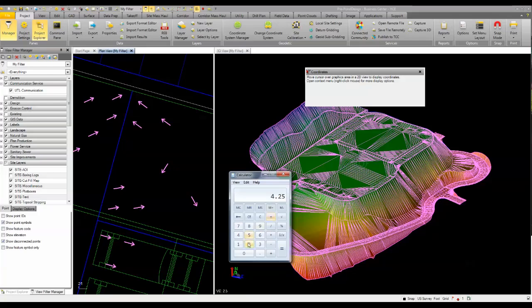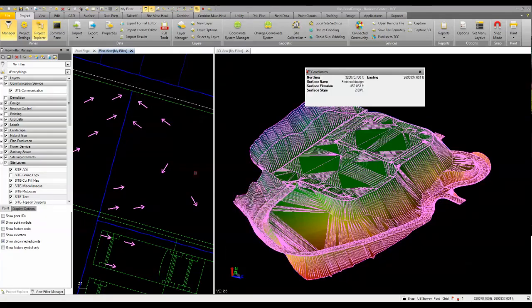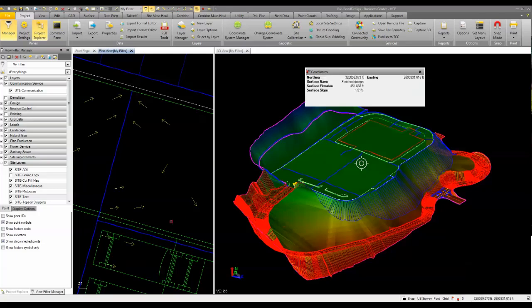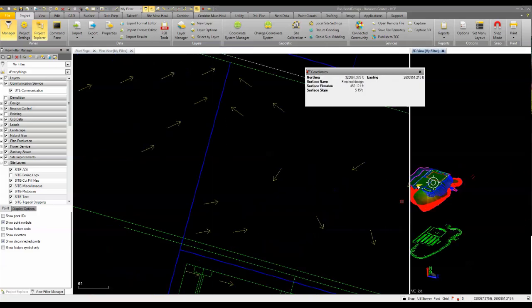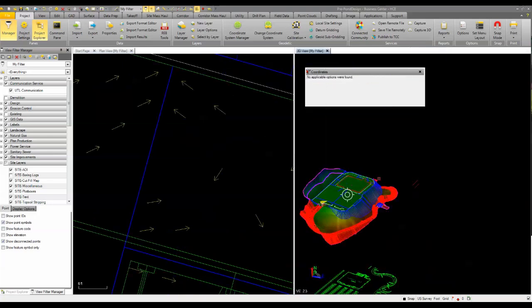So our top of pond elevation, let's say, is going to be at 444. So right, we had 448. We're going to drop another 4 feet, 444. So that's the magic number that we're going to start with down in this area. So what we're going to do is some manipulation along our corridor, because our corridor is what's going to tie this location together.